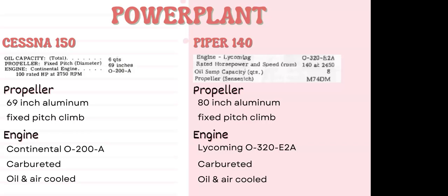We've got the red mixture knob, which is our fuel air mixture, and then we've got our throttle, which is our power. Both of these things are affecting the carburetor. The mixture knob is affecting the amount of fuel that we're getting into our air ratio, essentially. And then our throttle is dictating how much of that fuel air mixture we want to pump into the cylinder. So it's opening our gate from the carburetor into the cylinder. So it's dictating our power.